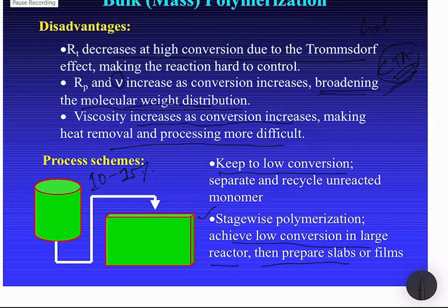Some local gel formation, some local heating effect and local charring effect, creating hot spots, meaning those local charring points. So that would actually make the quality of the polymer inferior. So this is another disadvantage, that is the quality of the polymer. Apart from being much wider in molecular weight distribution, otherwise the quality of the polymer sometimes does not remain very good or effective for the post application.